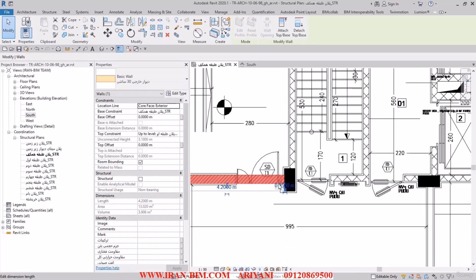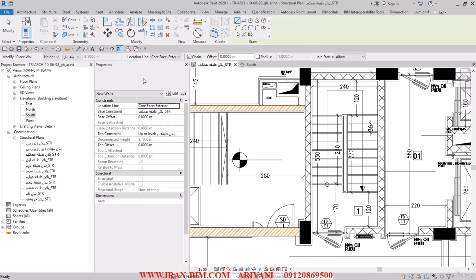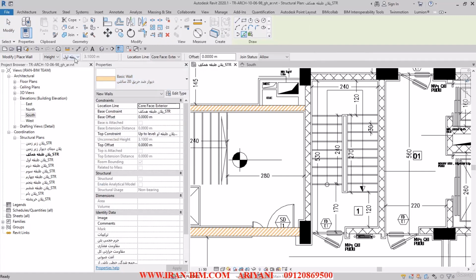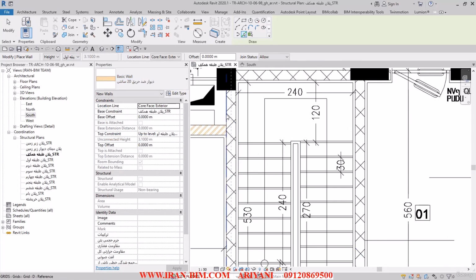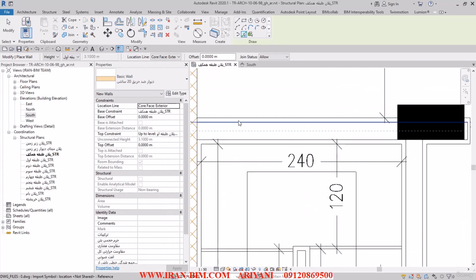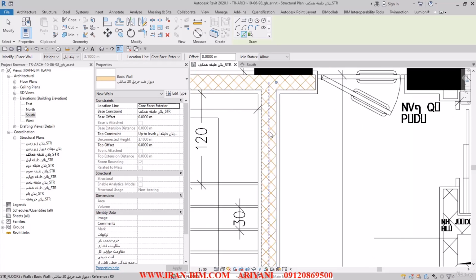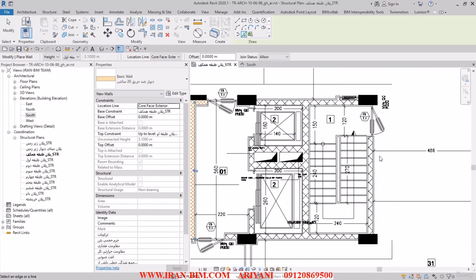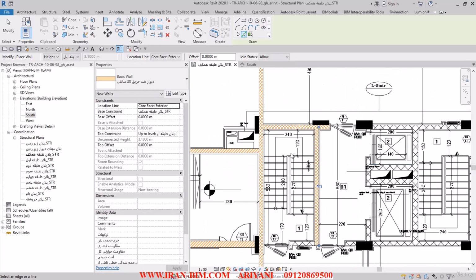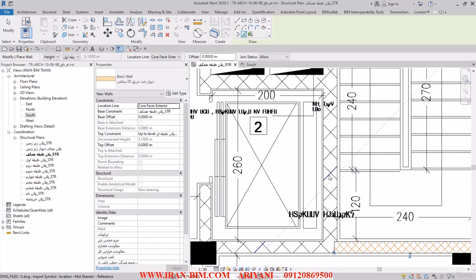So in the next part, we have thermal resistant walls. So from here, I open up the walls and I select the thermal resistant wall. That's 20 centimeters. So I select pick a line tool and then I'll start drawing. So let me just put this here and then we go over here. And then I draw this one here as well. After that, let's see where we need to go. I go down here and I select this one and I draw this one too.